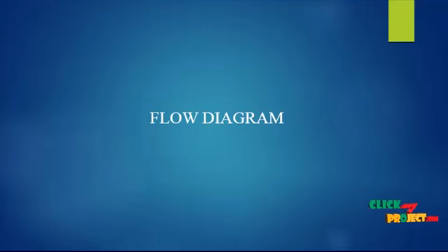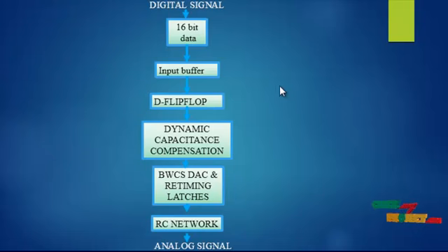Next we see the flow diagram of our product. In this product we use current steering digital to analog converters, which perform an important role in communication and video systems. Current steering digital to analog converters have the advantages of speed, linearity and power efficiency. There are three different architectures to implement the switched current source: array, binary and unary segmented, and they account for power consumption, chip size and circuit complexity.